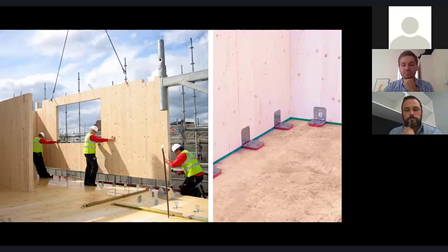Yeah, and it's just very slow on site to install those, particularly with nails, but slightly quicker with small screws, but still installers hate it and they hate you for it if you're designing it. Of course, you might have to on certain projects. I don't want to discuss too much, but on the right-hand side, you can see the rubber matting just for vibration and noise control or damping of the project, same with the brackets there. So that's more from an acoustic perspective, but just bear in mind what implications that has on your connection stiffness and stiffness of elements, because it will impact your shear stiffness of those joints.